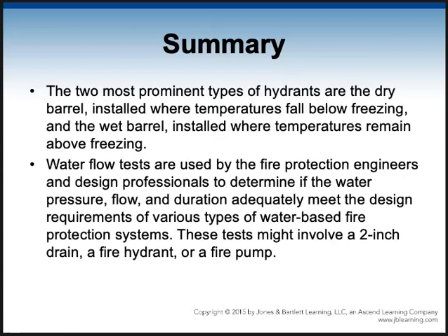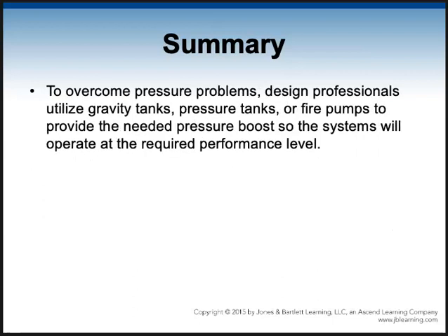And the two most prominent types of hydrants are dry and wet, and we talked about that. Water flow tests have to be done on all systems, not just hydrants, but sprinkler systems. We're going to test the pipe. We're going to test the different valves and make sure that everything is working the way it's supposed to work before we approve it and allow the building to be occupied.